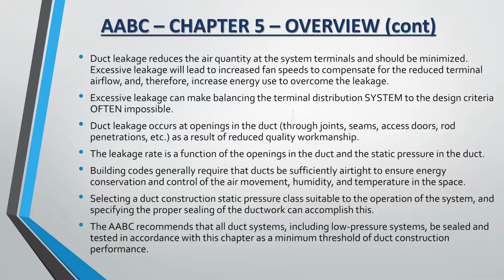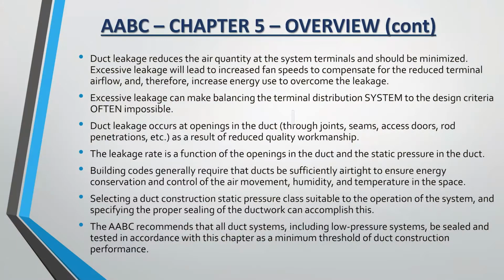Leakage rate is a function of the openings in the duct and the static pressure. Of course, as static pressure goes up, you're exponentially going to change your leakage rate. Building codes generally require that ducts be sufficiently airtight to ensure energy conservation and control the air movement, humidity, and temperature in the space. The temperature and the humidity in the space are key. The air movement is, in my opinion, a byproduct, but if you've got all that going into the ceiling and it's not meeting the space, you're not going to do the work that you want it to do.